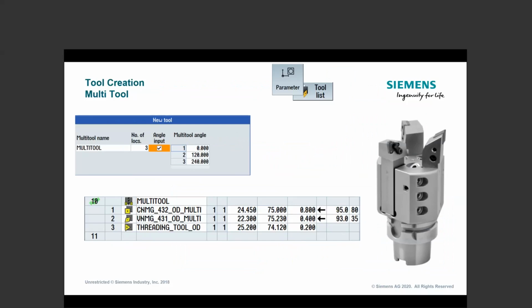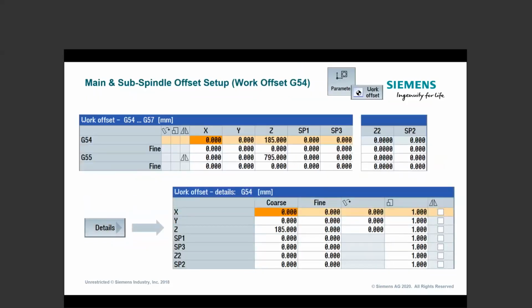So your machine may not always have a Y offset, but it can absolutely be added. When we get over to Sinutrain, we can take a look at that in a little more detail. But you can actually add an additional Y component to the specific tool. You always get that Y offset in the work coordinate like we're seeing here, but we can have a Y offset in the tool as well, in the tool definition.